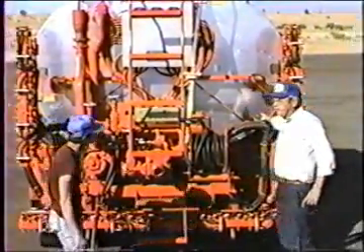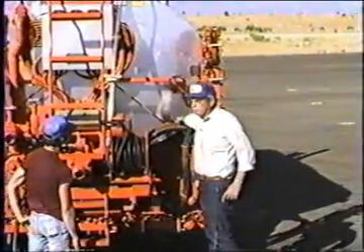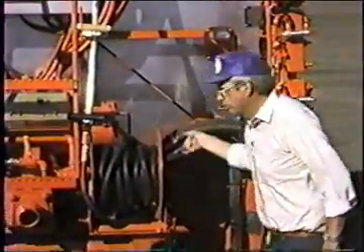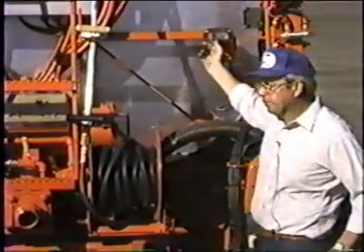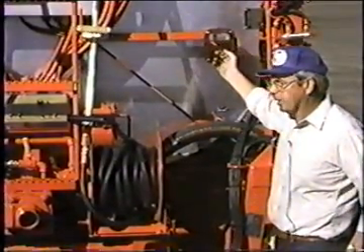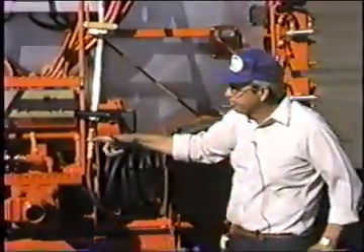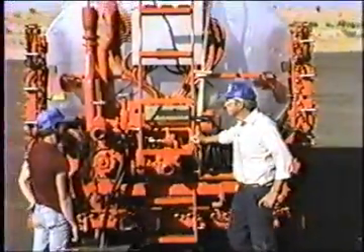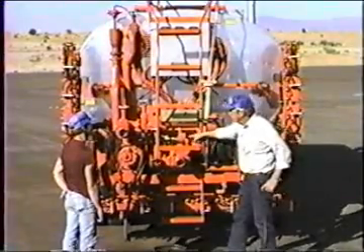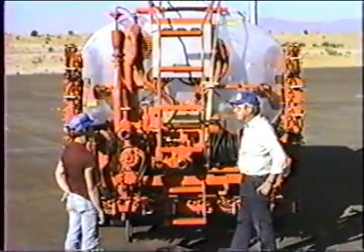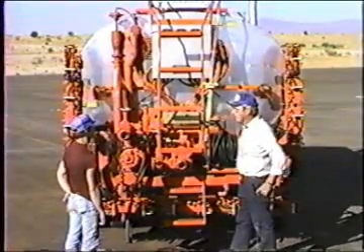Close the tank valve. The main tank valve, whether it be the air operated one we have here, the manual one with the lever, or if it were cab controlled, that's the final thing we'd do in the cab: close the tank valve. The pump is running in the forward direction, in the bottom and out the top. We just closed off the supply, we just closed off the asphalt.